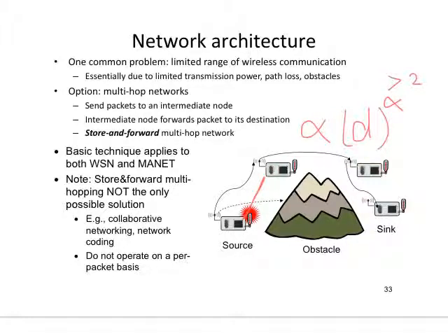The advantage of this is that the decoding itself has a certain probability of error. So if you decode and then forward, you enhance the bit error rate. You enhance the probability of error because you are decoding and converting. However, if you keep the signal in the analog domain and just amplify it, then the probability of error is... amplify noise, exactly, because you amplify noise.